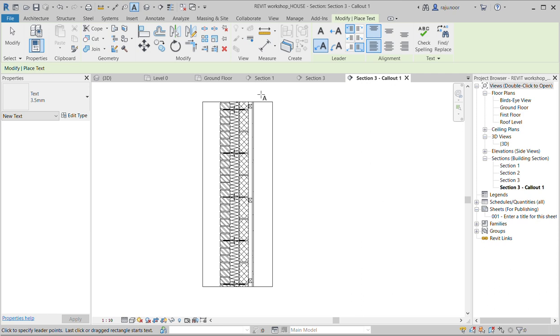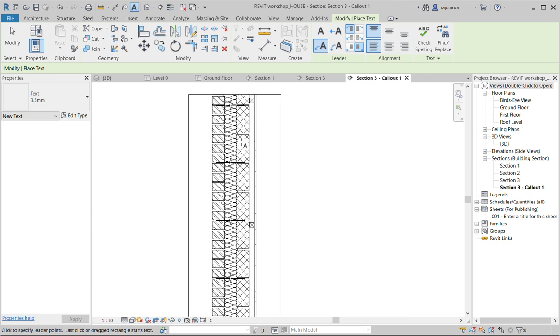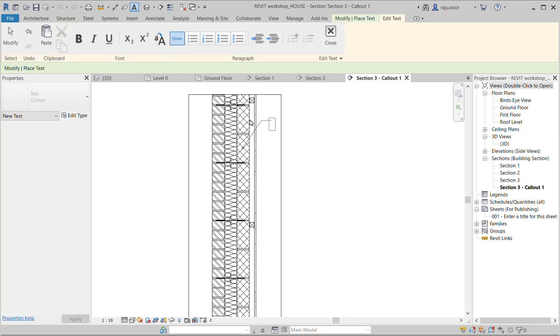I've gone on a manufacturer's website to find this kind of detail specification. So to add in a detail annotation, I'm just going to add in the first one. If I click on the blockwork, then the leader will come in again, the second leader will come in, and then I'll get the text box. Once you're in the text box, it's like adding in any other text.